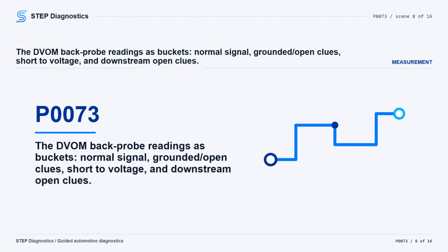If the signal is constantly above 6.0 volts, look for the signal circuit shorted to another voltage supply. If the signal is a constant 5.0 volts, that points to an open farther downstream, most likely the sensor or the sensor ground side. If the path takes you into disconnecting the sensor and ECU connectors, check the signal circuit for high resistance and short to ground.